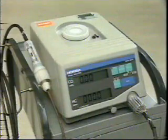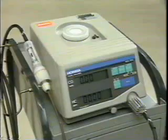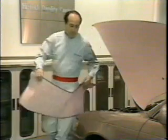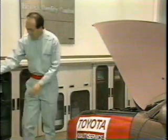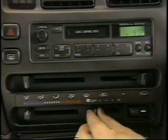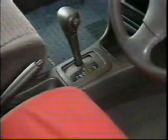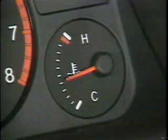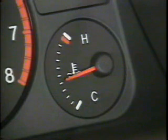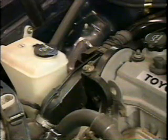Now, let's see how to adjust the idle speed and mixture. You should use a CO meter to do this if possible. First, in order to adjust the speed and mixture properly, we must make sure that the following conditions are met. Make sure that all the electrical accessories are turned off. Check to see that the transmission is in neutral. Make sure that the engine is warmed up. Confirm that the ignition timing is set properly.